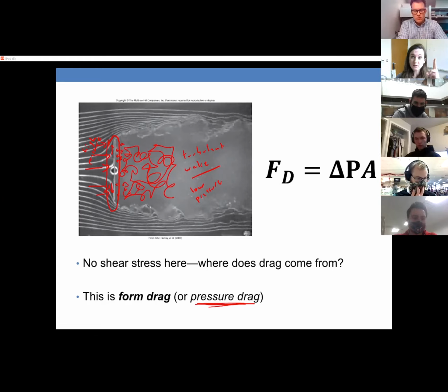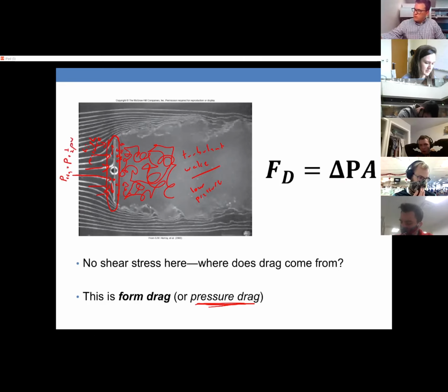All right, so two things. First of all, this front area: remember when we said that stagnation pressure applies when the flow hits this, the velocity right where it hits will be 0, and so the pressure would be the stagnation pressure, which is P plus 1/2 rho V squared.